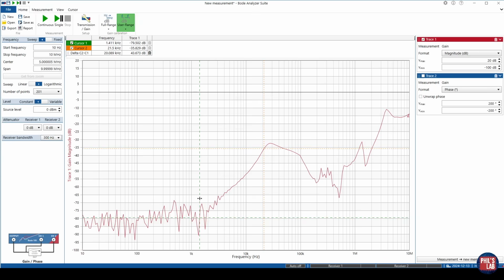One of them is, of course, the control loop of the regulator itself. Typically, control loop bandwidths are only in the order of kilohertz or tens of kilohertz. The bandwidth meaning the regulator can only react quickly to disturbances to the input voltage in that frequency band. Out of that frequency band, the negative feedback due to the reduction in open loop gain isn't as effective, and we let more AC input disturbances pass through to the output, and that's exactly what we're seeing here.